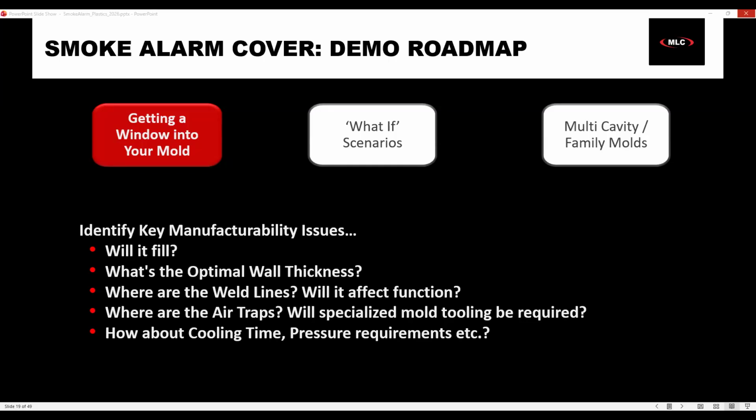There's a couple different types of simulations you can run. Right now, this is running what's called a fill simulation and a pack simulation. The fill simulation is the very basic type that you have to run. That's the bare minimum. The fill simulation is going to give us results on the fill time. Will it fill? Short shots? We're still going to get weld lines, a lot of that basic functionality.